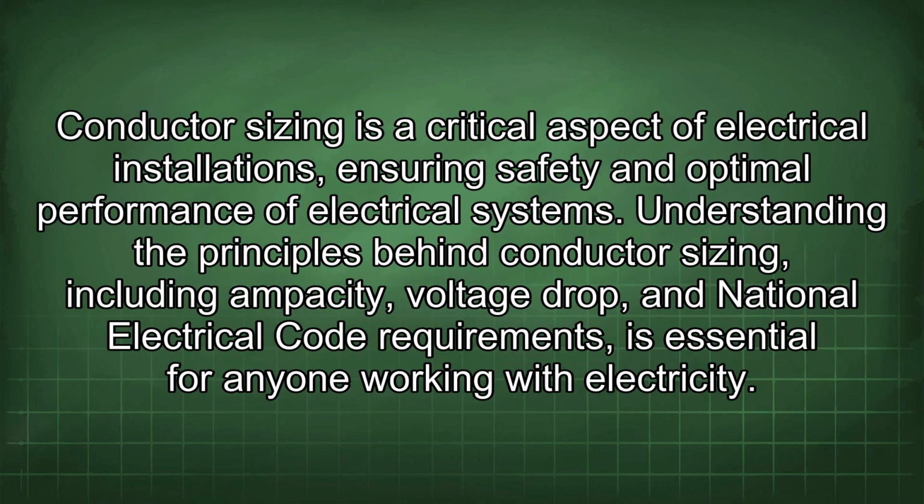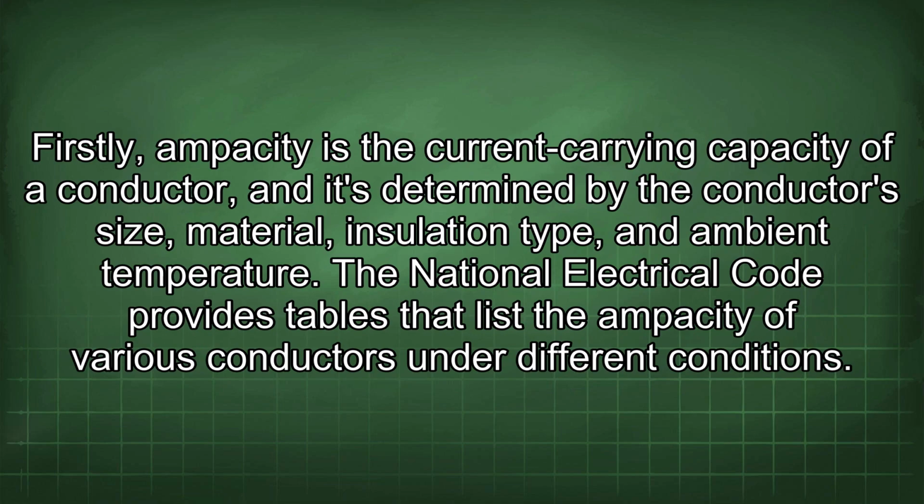Conductor sizing is a critical aspect of electrical installations, ensuring safety and optimal performance of electrical systems. Understanding the principles behind conductor sizing, including ampacity, voltage drop, and National Electrical Code requirements, is essential for anyone working with electricity. Firstly, ampacity is the current carrying capacity of a conductor, and is determined by the conductor's size, material, insulation type, and ambient temperature.